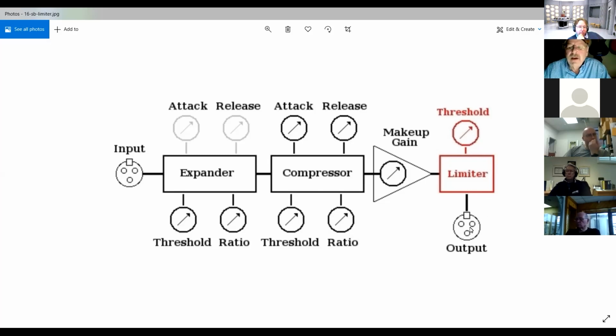And you probably know you could overdrive an old tube input and it wouldn't be too bad unless you really drove it hard. Overdrive a solid state input could be bad, especially older germanium transistors. It could be pretty nasty sounding. You overdrive a digital input, it's going to go insane. It goes into what the programmers call undefined behavior, which basically sounds like hash. You know this. If you've ever overdriven a digital input, you might get sputters, you might get dropouts, you get breakup. There is nothing pleasant about it.